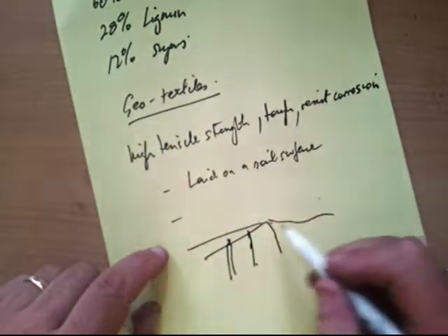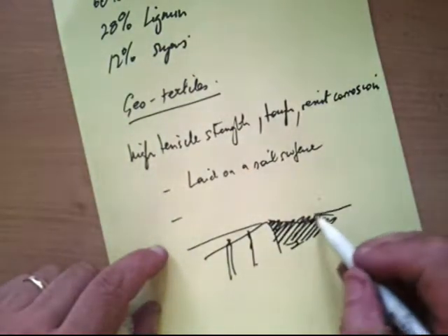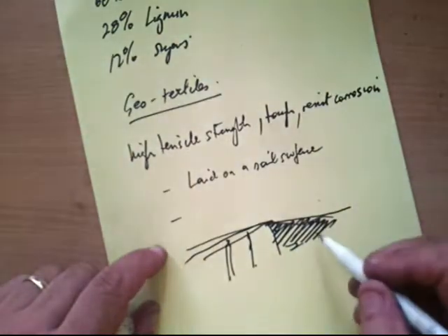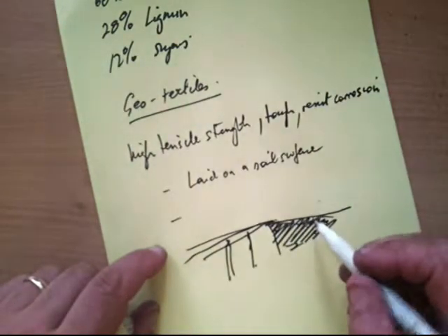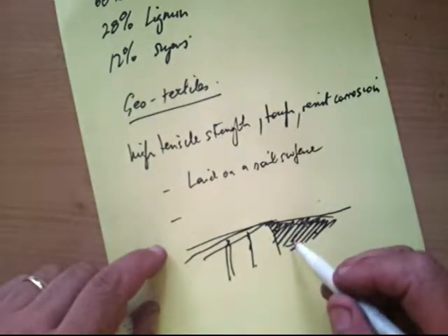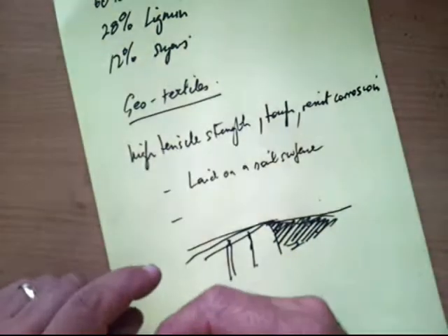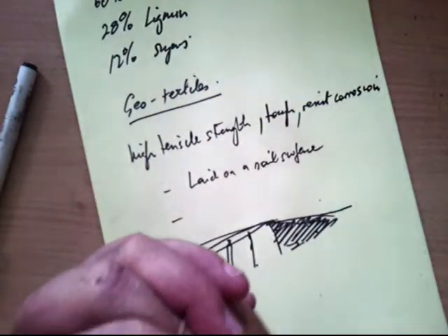And very frequently that's necessary when you've got a bridge that's passing through somewhere, and the bridge is suspended like this, and on the lead up to the bridge you've got a hill, and the hill is made of some sort of dirt that's been built up there to allow the road system to travel through. But this, if it begins to erode, will destabilise the whole bridge, so geotextiles are laid over this area to be able to keep it stable and structurally sound over time. So a very useful material.